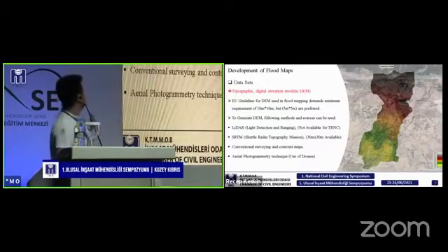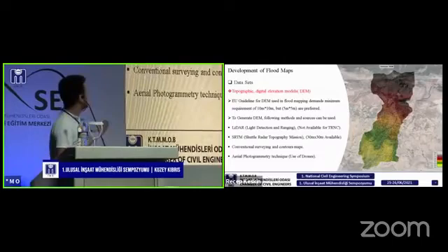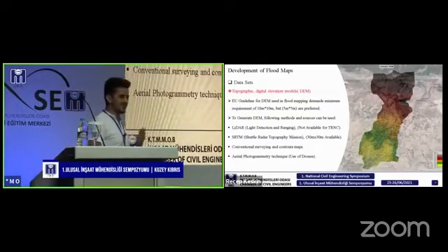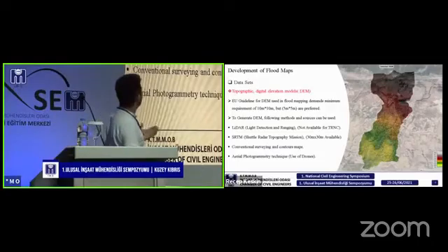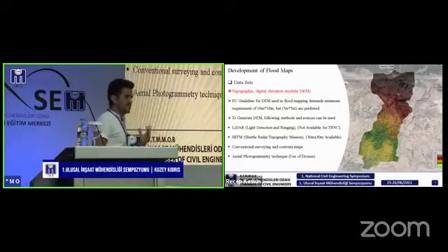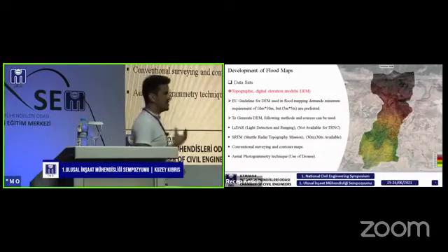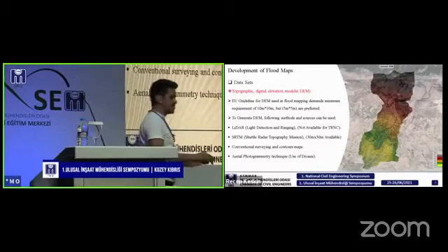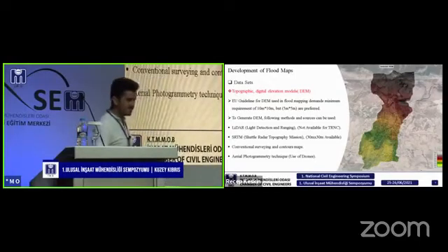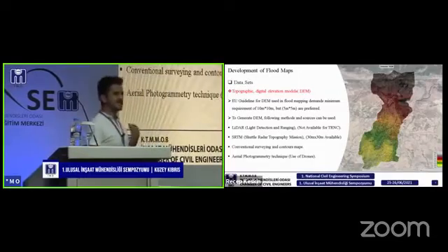First of all, it's topographic data, also known in our part of the world as digital elevation models or DEM. So according to the EU guidelines, the DEMs, digital elevation models that are used for this, they should be minimum 10 meters in cell size. Like in each 10 meters, we have to have the elevation, but 5 meters cell size data are preferred.